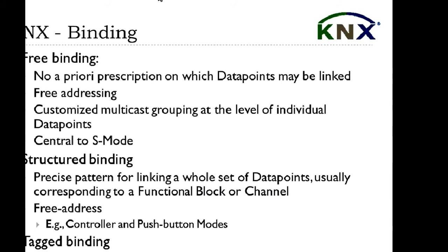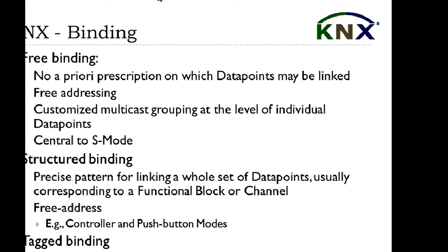In that case, when I push the switch, it writes a 1 on the group address, on the multicast address. All the devices are listening for this new data point value and take the action. And so we have realized the scenario, for example, switch all on, by just binding the data points together.